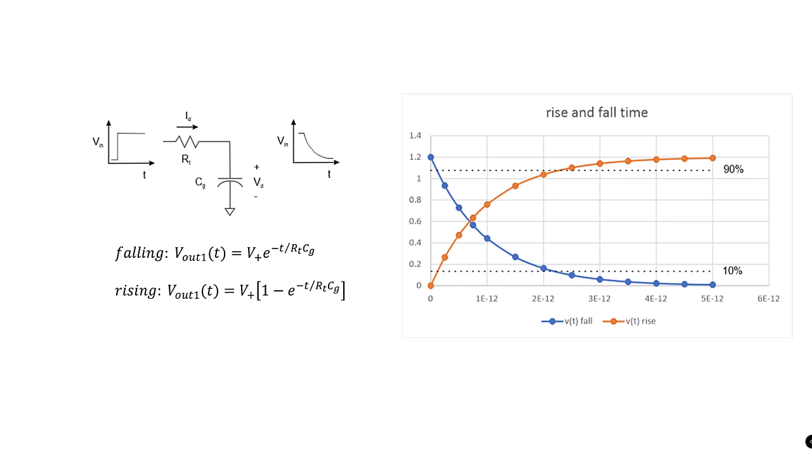We can measure the delay through a logic gate from one input voltage to another. A typical pair of values to compare is the 10% voltage and the 90% voltage. We can measure the rise time, or the amount of time it takes for a logic gate to rise to a logic 1. We can also measure the fall time, the time it takes for the output to fall to a logic 0. In many cases, a logic gate's rise time and fall time are different. That's because P-type transistors are not as efficient as N-type transistors.